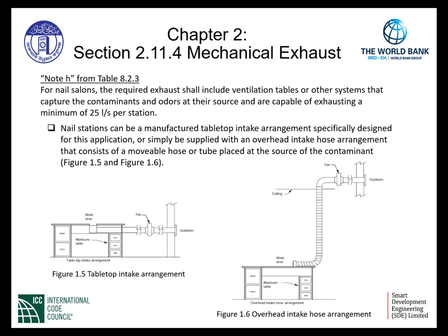Figure 1.6 gives us another application where we have a flexible duct that is placed on the work area, a manicure table. This would be the source capture area. The customer would place their hands on top of the table, and the contaminants would be captured at the source. At the source, we again need 25 liters per second right at that location. The contaminants would be exhausted up that flexible duct into the inline fan and exhausted completely to the outdoors.